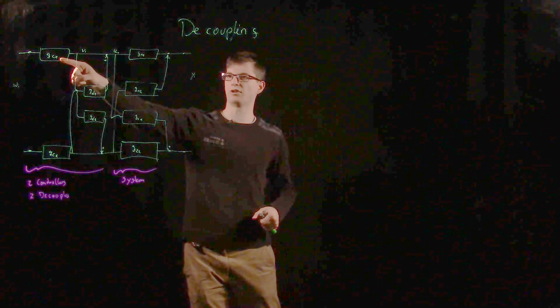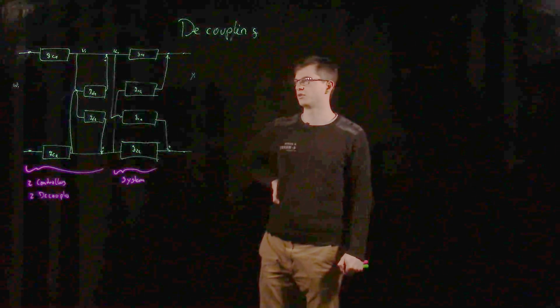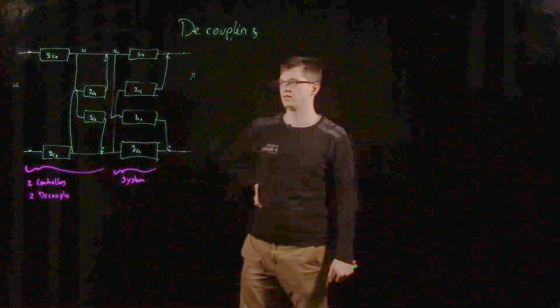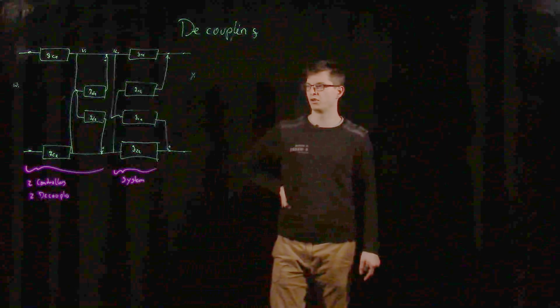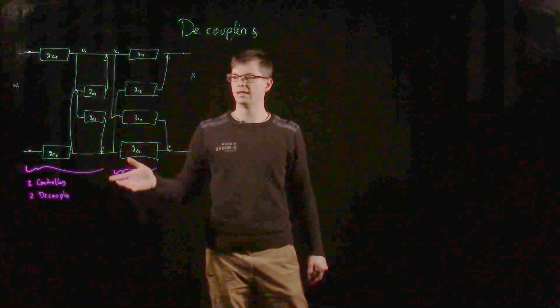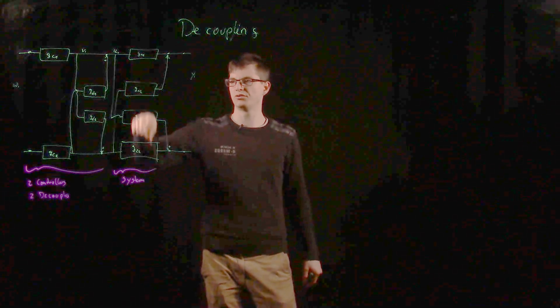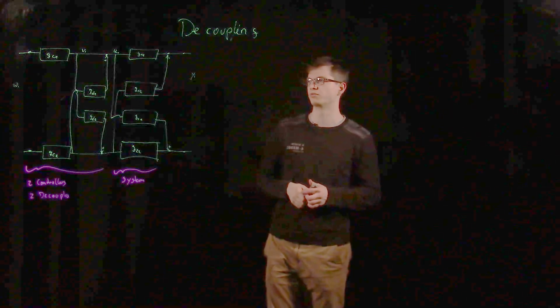They have the direct control for our output variables, so those GCs. And on the other hand, the decouplers are implemented as well. In this video, we want to design these decouplers in such a way that the interaction between those control loops is excluded perfectly.